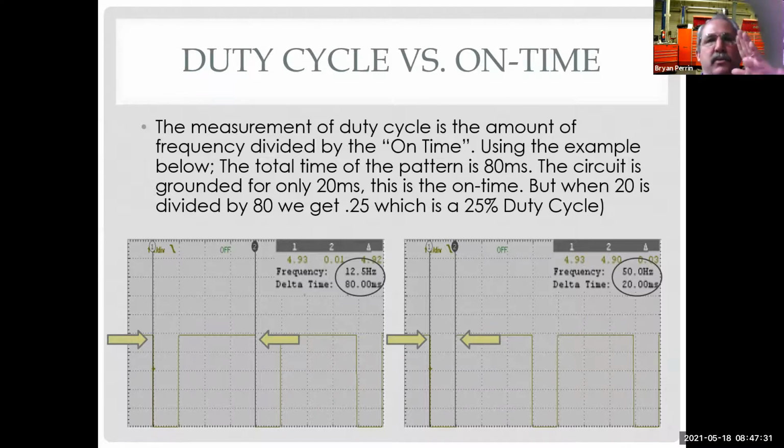So what this allows us to do is say I have a solenoid with a plunger in it. If I only have a 5% duty cycle, we're only energizing it 5% of the time. So I'm going to get a little bit of lift, right? Because I'm doing it very quickly. If I get to 50% duty cycle, now I'm going to be about in the middle, and at 75%, 3/4 up. So I can change the opening of something that's linear with a digital signal.